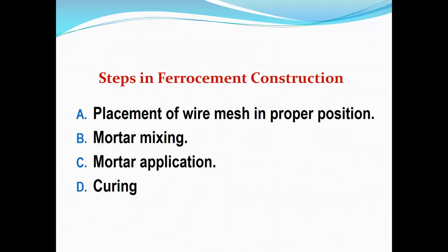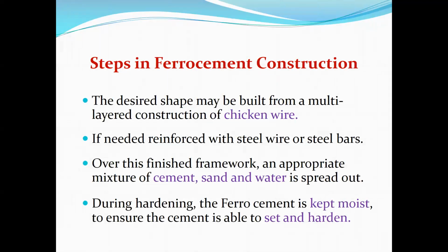Reinforcing mesh, so that means the iron bars are placed closely spaced. The steps in ferrocement construction. There are 4 steps, simple. At first, you place the wire mesh in proper position. Then you mix the mortar and apply the mortar, and then we allow it to cure. If you go into the details,